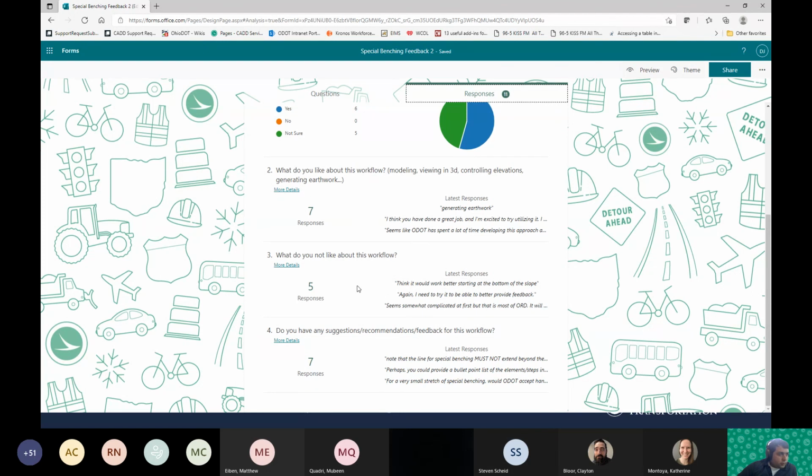Just before we ended, I saw one. I meant to bring this up about starting at the bottom of the slope. The way the GB2 note reads, it just reads more top down, as well as if you start at the bottom, now you've got a lot more to worry about at the top if you're going too far in, like tearing out more pavement, things like that.